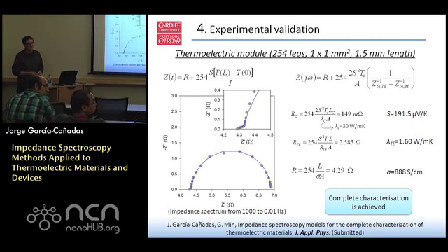So you showed Bode plots as well. Is there any information that you get from those? Usually, the reason I work mostly on complex plots is because it's more sensitive, so you easily see all the trends. In Bode plots, this is usually more difficult to identify. So a Bode plot, in principle, has an S shape: you have a constant, a drop, and another constant. So you only see the difference between this point and this point mainly. For example, this trend is difficult to see in Bode plots.